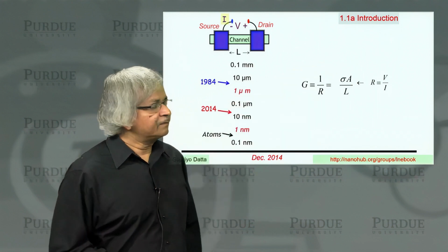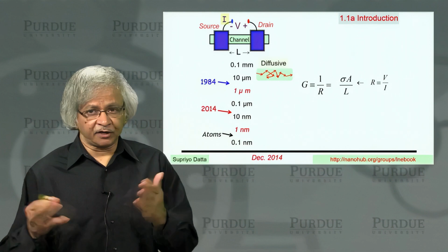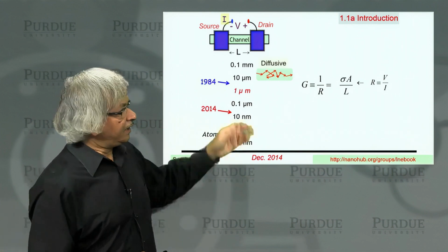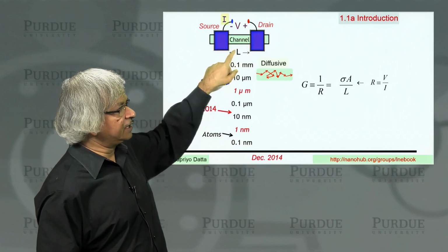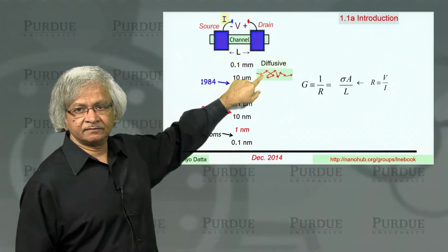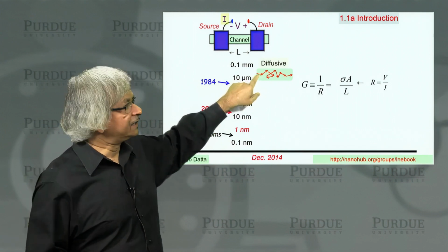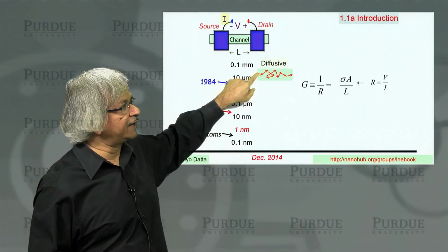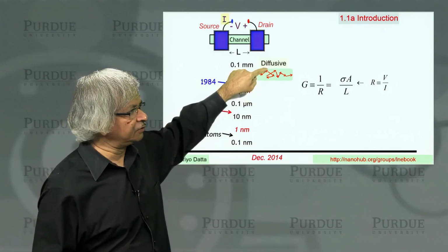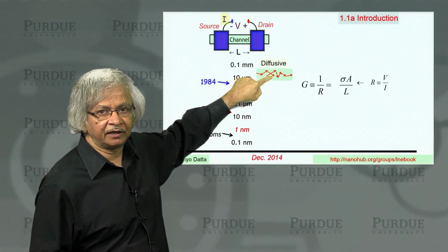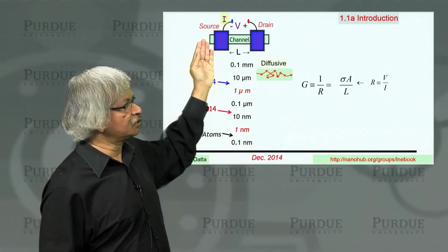Well, usually the way we think about conduction, the way you'd learn about this in, say, freshman physics, is that electrons travel inside your conductor through a diffusive process, what sometimes people refer to as a random walk. An electron comes in from one contact, goes along for a while, hits something, gets turned around, hits something else, gets turned around again, and so on. And that's how it eventually gets from the source to the drain.